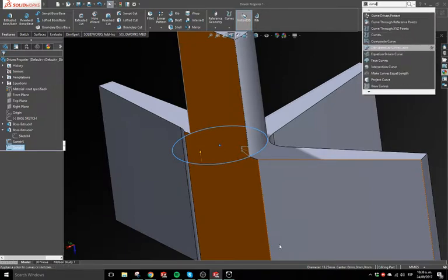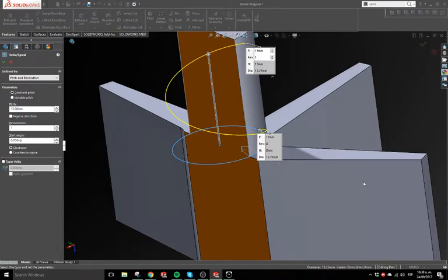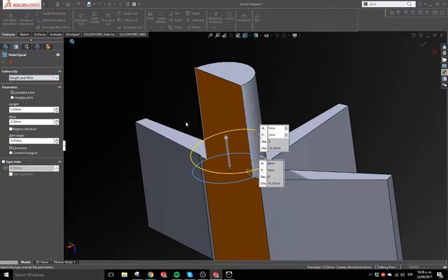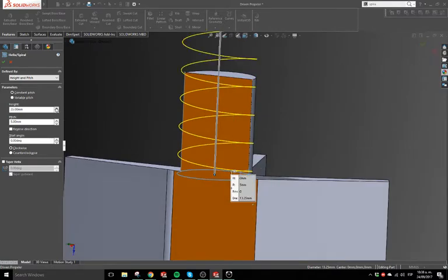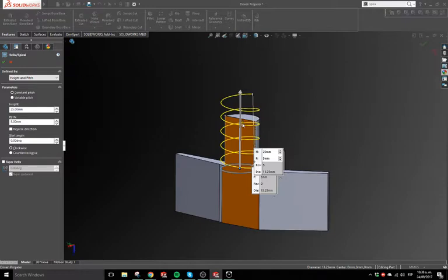And another cheat that I can share with you is spiral, helix and spiral. With pitch we do 5, and we do it by height and pitch. We can exit it because it's a cut relationship, so you will just not cut anything after it, which is what we want.